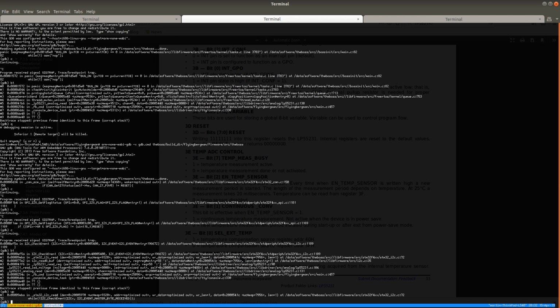I know I have to rewrite this I2C driver, I have that on my to-do list. This I2C driver is the worst driver in this firmware. This is a blocking, horrible I2C driver that consumes 50% of CPU power. But even if this driver was timing out here, this would still not return the data. So I'm trying to figure out why it actually doesn't return any data. Why is there no response from the chip?